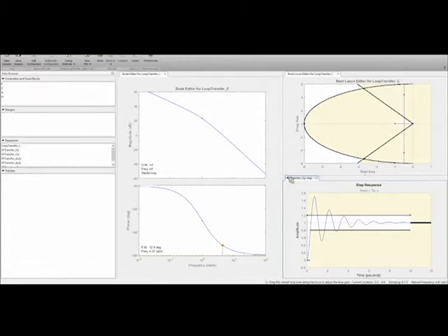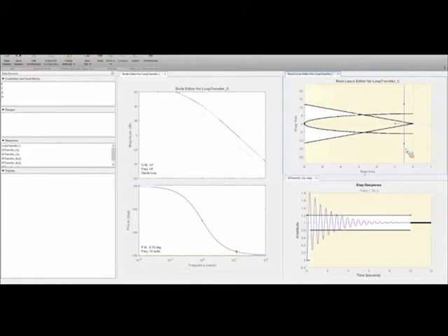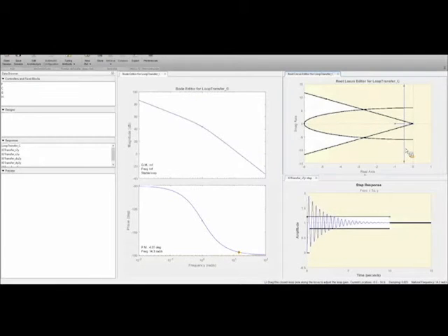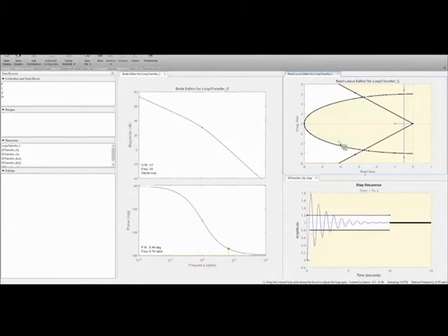All right, and so then we can see that we can start to meet this rise time constraint if we increase the gain a little bit. All right, so there we're definitely meeting the rise time constraint. Whoops, it's overshooting a little bit. All right, move it back to here. Okay, so here we're meeting the rise time constraint, but the overshoot is nowhere near being satisfied, right? It's way overshooting that response. Okay. All right, so this is where we started in terms of proportional control.